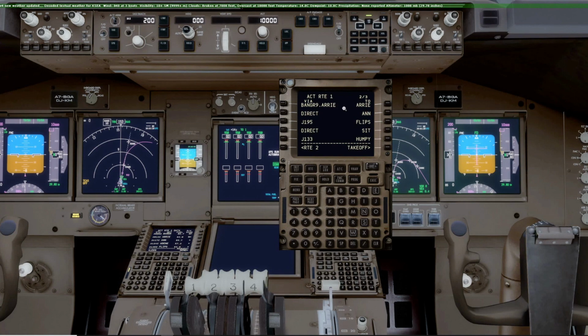If the first officer were the one to do the courses and distances, then if I'm the captain, I don't need to recheck that. All I need to do is check to make sure the route's in there and it agrees with the flight plan. And I'd probably go to progress and check that the distance to Anchorage matches the flight plan, that it's reasonable. The other guy has checked the specific courses and distances. So again, both crew members don't need to do that, just one.